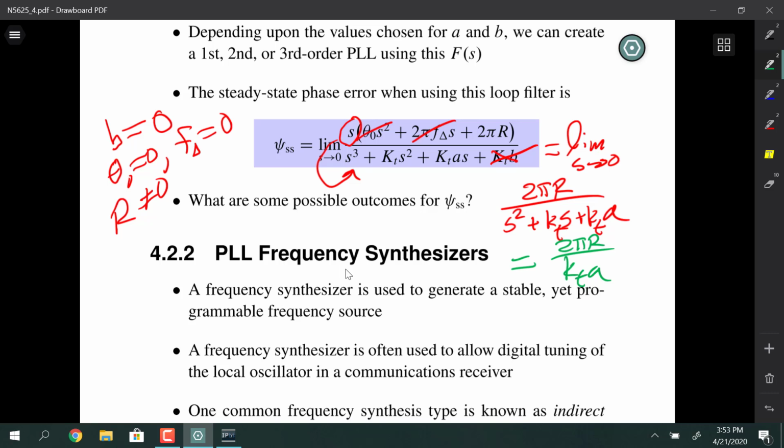So what it's telling you is that for a second order loop with a frequency ramp type of platform dynamic, the steady state phase error does not go to 0. It's some number. And so in certain types of platform dynamics, like in a highly elliptical orbit, when the satellite flies overhead, say out here at Schriever, where they have a monitoring station for the AFSCN, there might be a really high platform dynamic as it's whipping around and then flying off again.